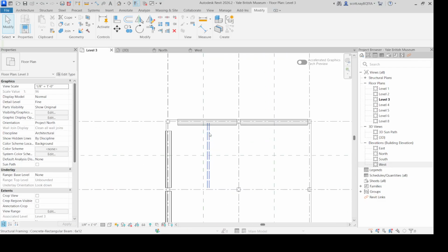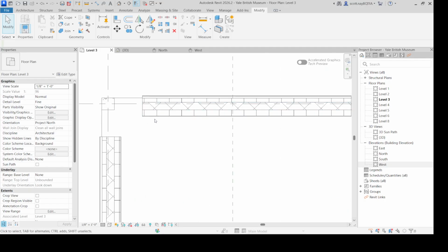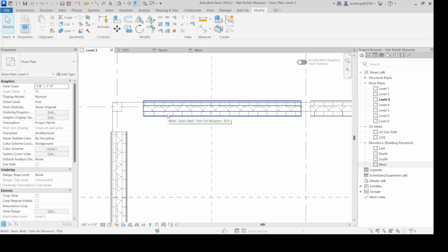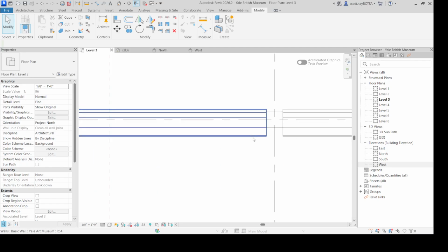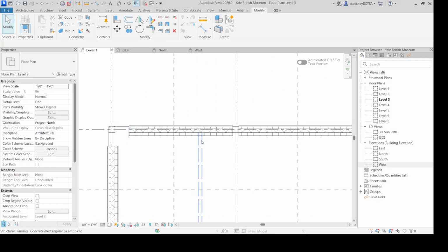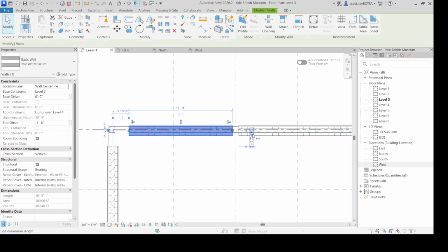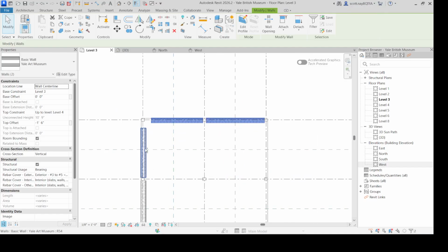All right, I'm going to come back in here. And what we want to do now is we want to take this wall and turn it into parts. And once we do that, we can start using shape handles to drag things into place. Again, we're going to leave this outside exposed, but inside we're going to cover with insulation and wood. So I'm going to click all of them really. And right here is this create parts thing. So it's just to the right of measure and below create assembly.